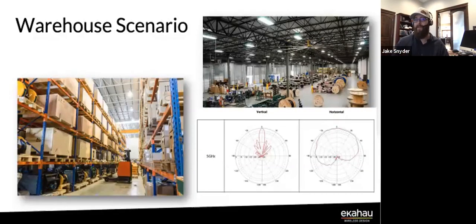Suddenly you were planning on a 13 dB antenna with 20 dB of transmit power, and you can only use 15 because the FCC limits that. So you have to make sure either your manufacturer supports the antenna gain you're using, or that you're still within regulatory compliance.